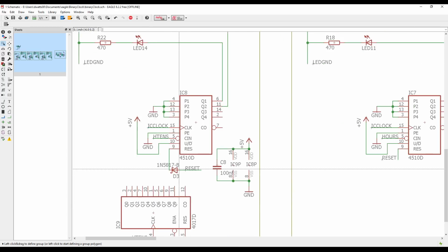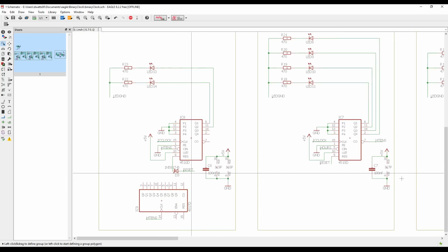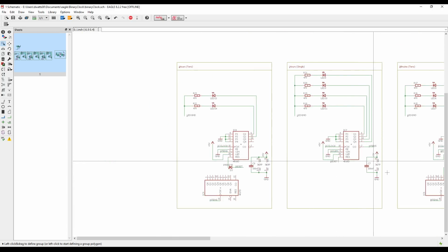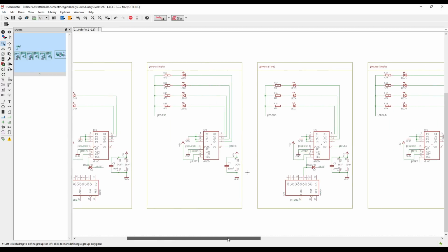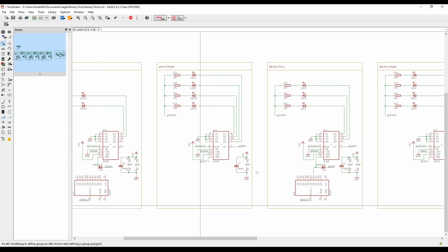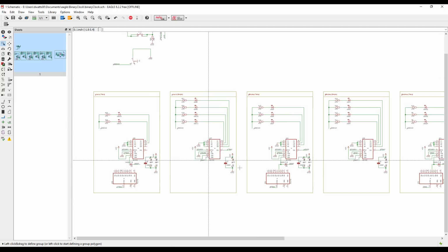And I found that I needed to have reset lines with diodes on some of these. So where I've got the 4073 going to reset chips, if I just press reset on one, it's actually still connected to the hours and the seconds and minutes. So it ended up resetting the whole circuit, and at the wrong time as well. So diode steering is essential for this at the moment, and I need to put those in the right place because it actually should be on the...